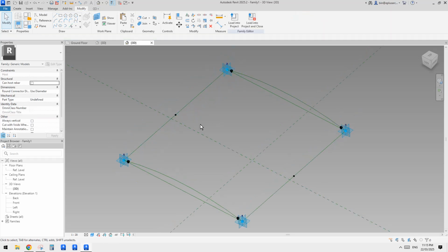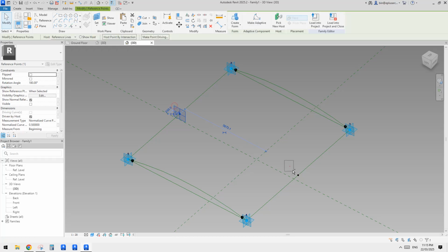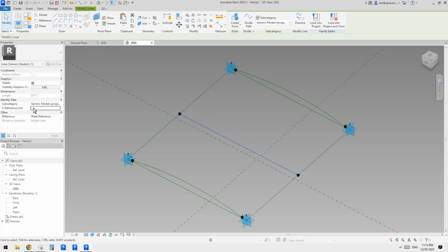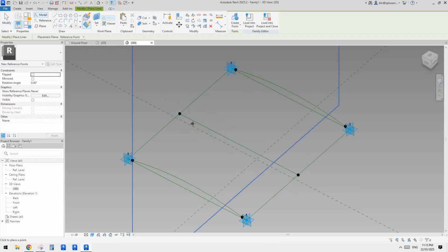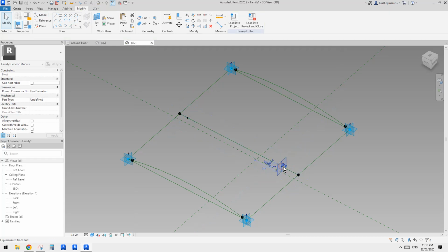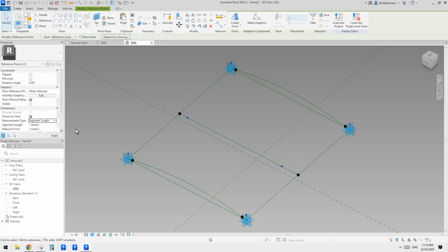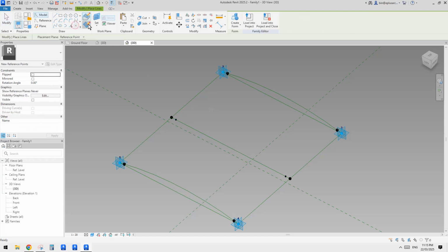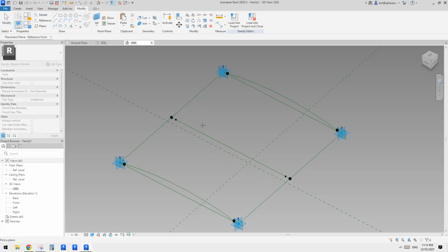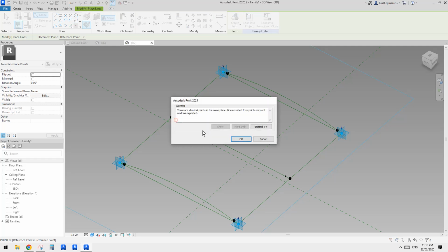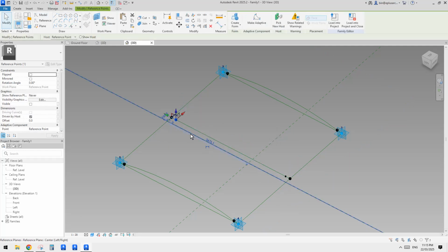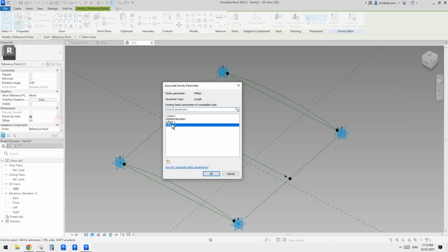So for this one, I think, yeah, we can do the same. We can select these two, spline through points, reference line, point, draw face, place it here, select this one, yep, correct, flip, and we can select them, segment length. For this one, maybe just use 200 as well, right? And then place point, draw world plane, set world plane, tab, place it, okay, select offset. So this time we're going to use offset 2.